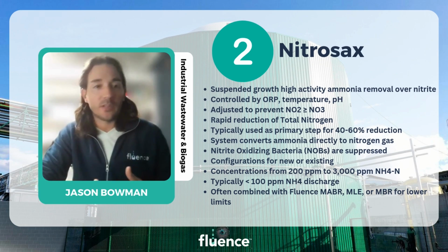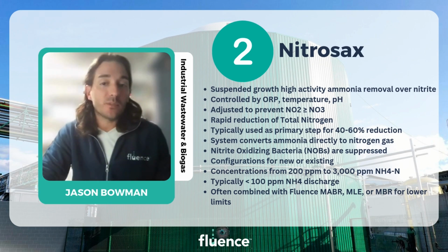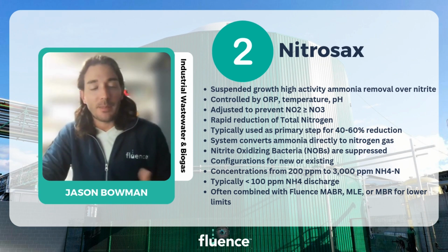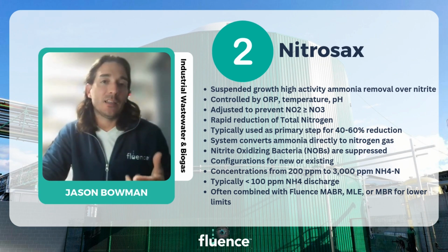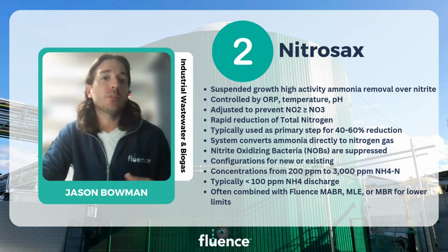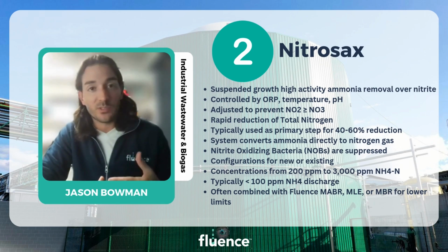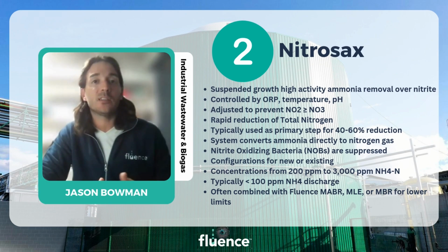So the benefit of this technology is that it can accept high COD, it can accept high nitrogen loads. There's really no upper limit to the ratio. And it's reasonably flexible with ionic activity, so calcium and things of that nature. The main disadvantage is that we typically only design for 40 to 60% removal efficiency with these systems. Like I said, it's the first step in a more complete biological system. The reason we don't design for more than 60% removal efficiency is beyond that, it becomes difficult to maintain the proper biota in the system.